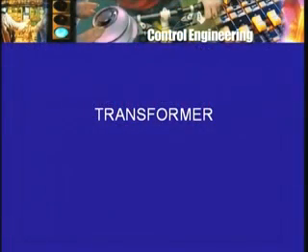So one has to make a choice: shall I use an AC motor which will run directly on what is provided to me, or that may be expensive. I may therefore use a transformer to step down the AC voltage to a level such as say 230 volts RMS, and then use an AC motor which will run on that lower voltage. One has to make a choice. Now from a practical point of view, such a choice is very important, because ultimately you have to put something there. You can't say do anything, put something. You have to know what you are going to put.